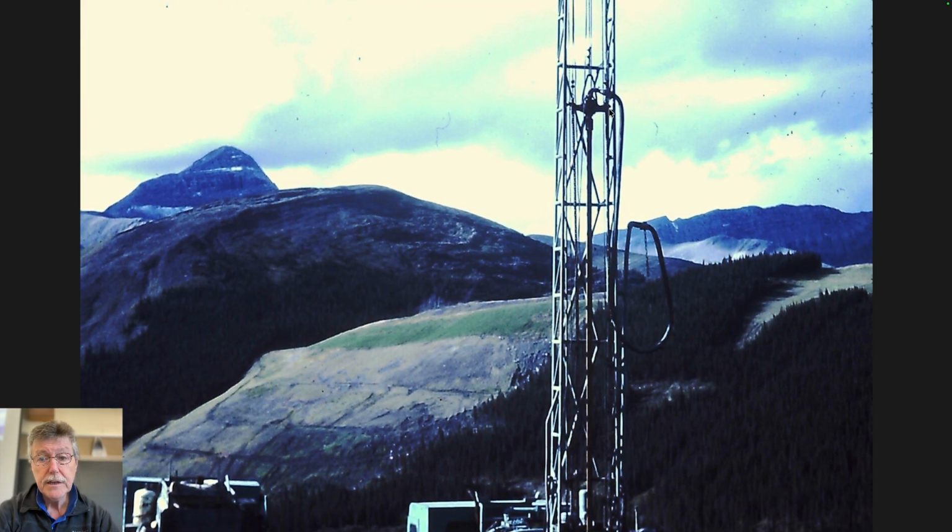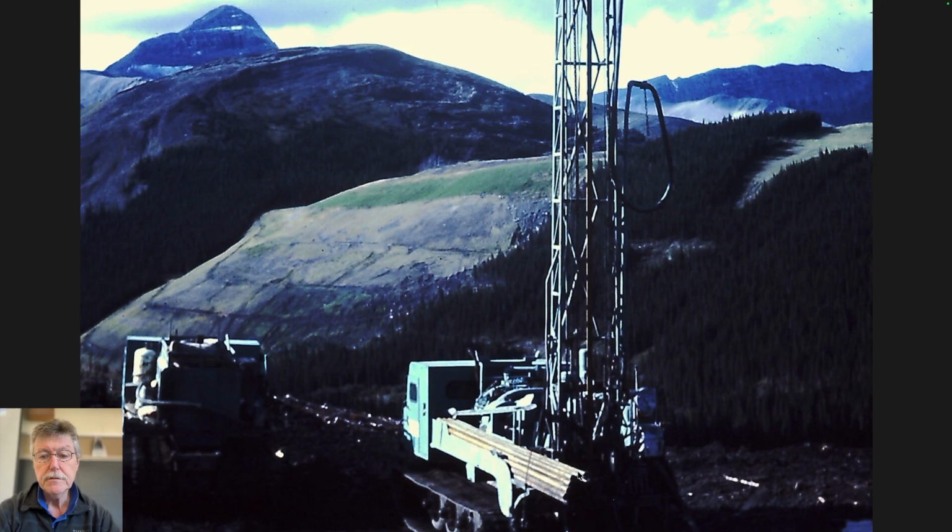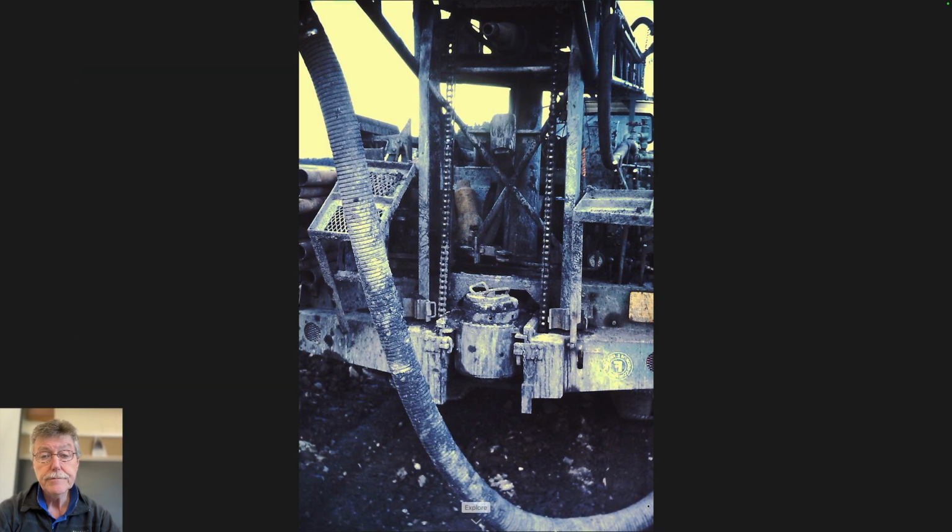A piece of drill rod in here with water, drill fluid being circulated up into here and then down into the drill bit for it to go through. Again, this is where the drill steel would go. This chain is to physically pull weight down, the weight of the truck, I guess, against the drill bit to be able to advance it by rotating it in the bottom of the hole.